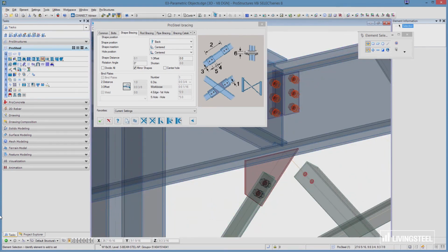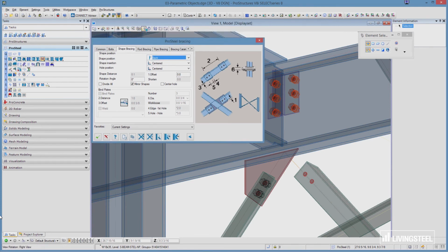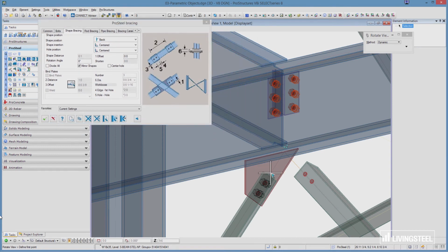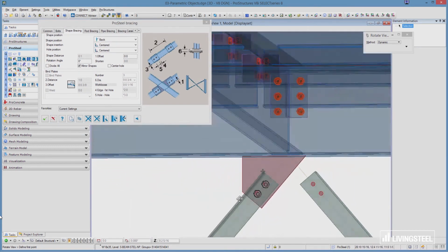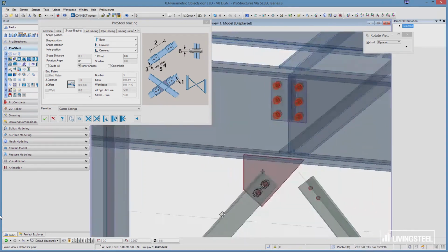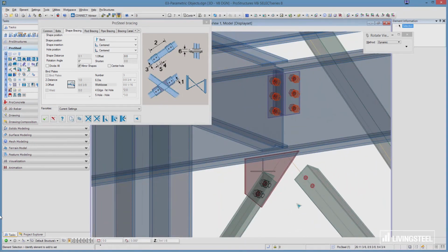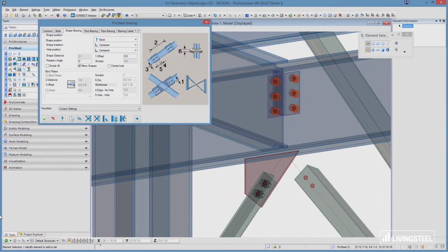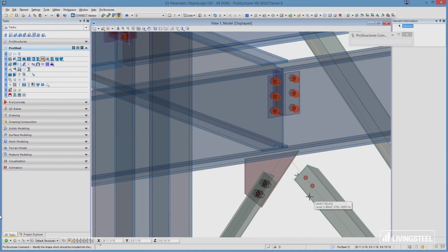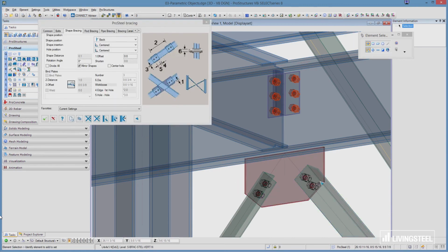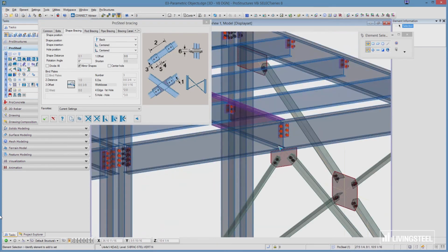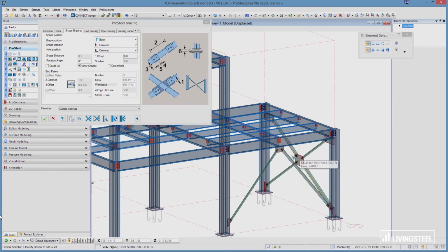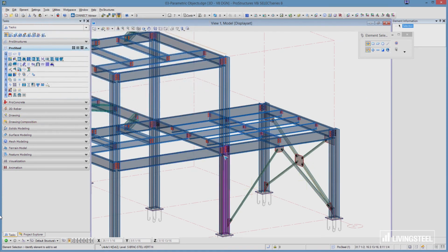Now let's look at it, and this one, is it on the right side? It seems to be okay. Let's maybe rotate a little bit to make sure that it is okay. Move this here. And it is okay. It is on this side. Perfect. So now what I need to do is simply tell it I want to add, with this button, add this element, and the gusset automatically grabs that other element. And I'm done with these two bracings. So that was for the bracing command.